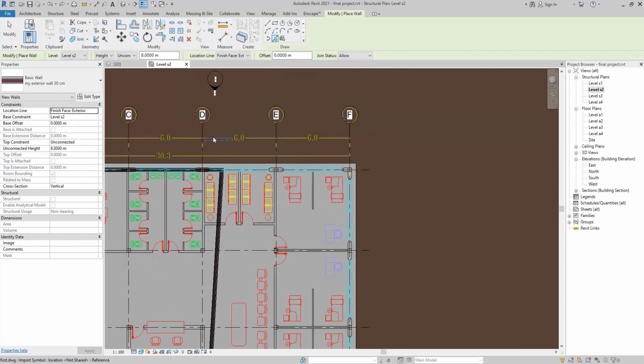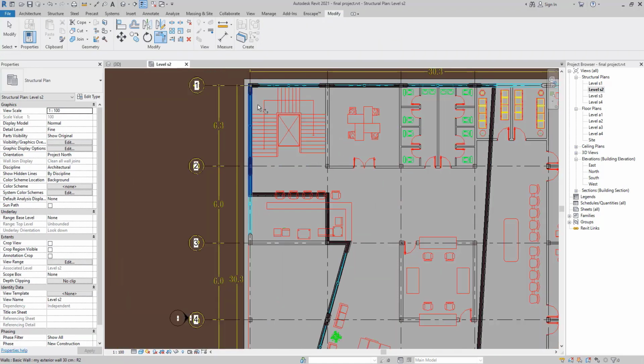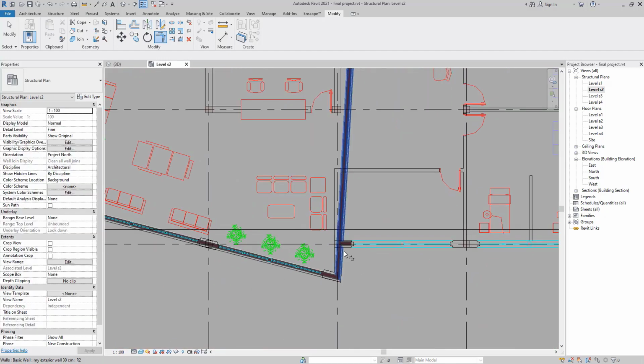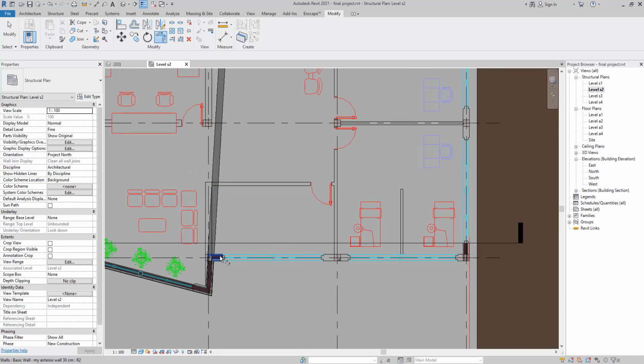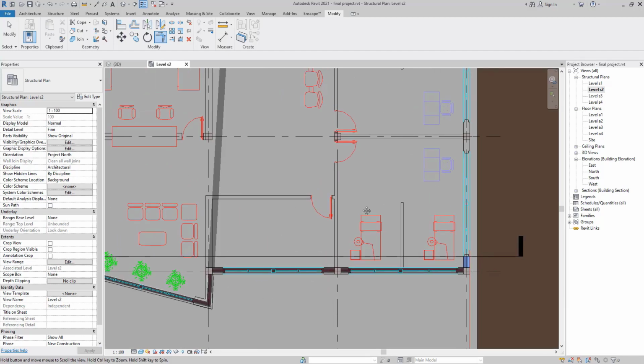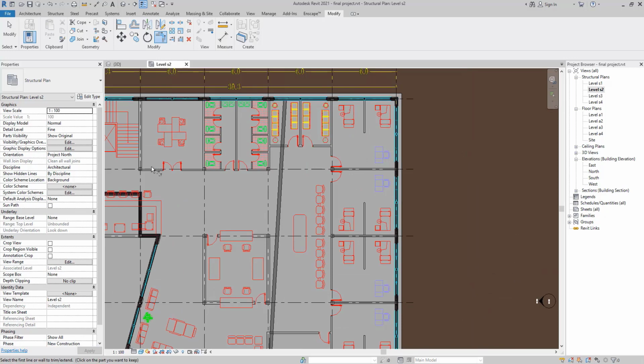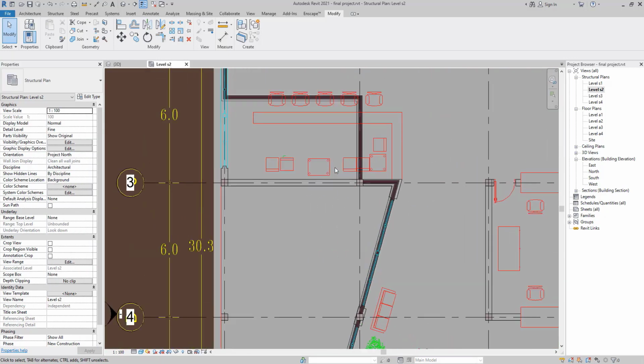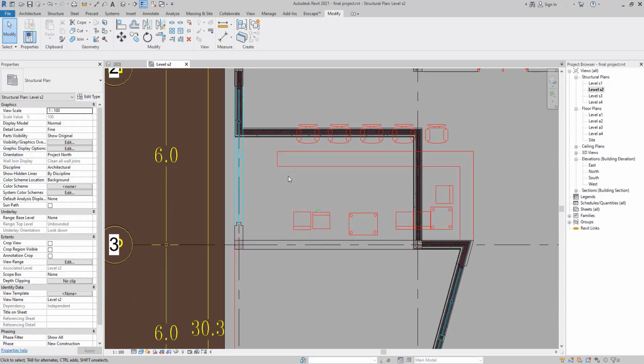and we are done. Now we will go to the trim extend by using the shortcut TR, and we are going to trim the place that we need, for example, here to here, here as well, and here. So now we have our exterior wall all ready, but we need to change this place because it was an interior wall. So I'm just going to choose this wall and use the trim extend to choose this wall as well.